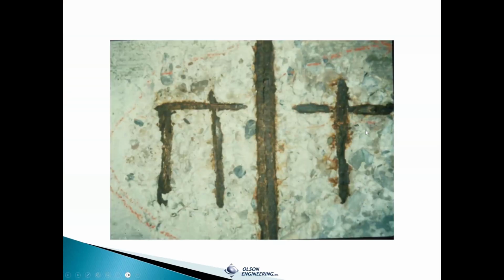And when steel corrodes, you can see it's going to go at a fairly substantial loss of material. It expands like 2 to 6 times. So every hundredth of an inch of corrosion might expand by 200ths to 600ths, which cracks the concrete, spalls it off, and ultimately exposes the corroding rebar. To check the amount of steel, you have to shine it up, get to bare steel, and measure it with the calipers to get the remaining cross section. But here are just some pictures of that corrosion damage.